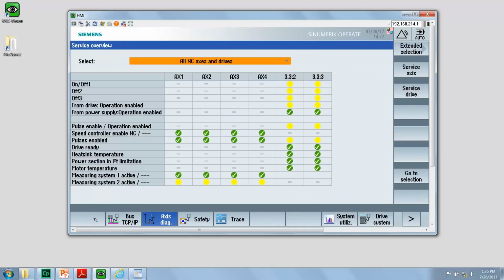Now, the top level of diagnostics is one of those things that's going to be very different depending on what version of UI you're running, especially with HMI Advanced. With HMI Advanced, the service access screen is about here somewhere. That's where you're going to be going instead of to the operate path. So, come into the diagnosis area, come over to Access Diag, select that. We get the screen. I'm in simulation, so don't worry about the fact that I'm missing most of my enables.